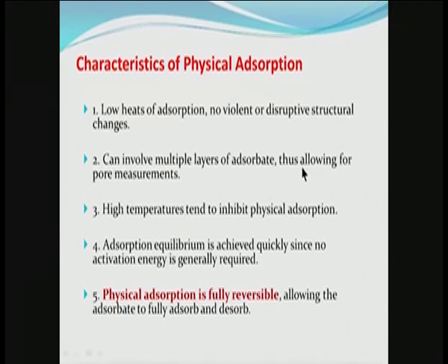So, the measurement of pores would involve multiple layers of adsorbate. High temperatures tend to inhibit physical adsorption. As I said, the heats of adsorption are low because there is only van der Waals attraction between the adsorbate and the adsorbent. Adsorption equilibrium is achieved rapidly since no activation is generally required.